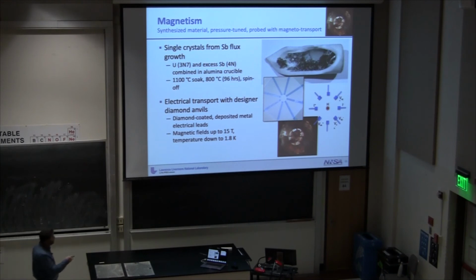So what that allows us to do then is put a sample in contact with those. So basically just plop a sample right on top of there. We usually backfill with some sort of pressure medium. In this case, it's a steatite, which is soapstone or chalk, basically. It's a very soft mineral. And you can see the sample is sitting there. Underneath it are the microprobes that are emanating. The nice thing about this technique, number one, is the microprobes are there. I don't have to do anything with them.